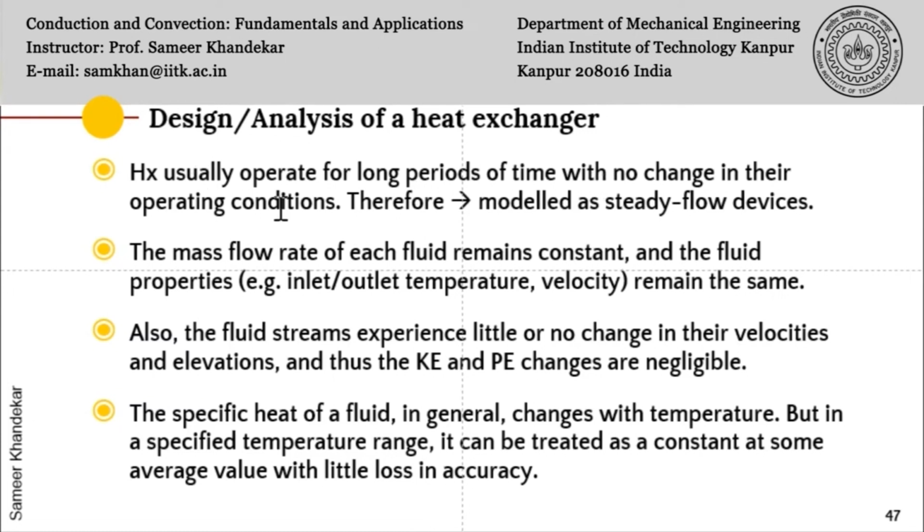Of course, as we have studied in the last lecture, fouling may take place over a period of time and the performance may decrease a bit. But then routine maintenance is done to clean the heat exchanger also. So almost all heat exchangers are modeled as steady flow devices. So we are usually not bothered about the transient of the heat exchanger because it is small as compared to the total time in which the steady state operation is desired. In fact, the transient is minuscule.